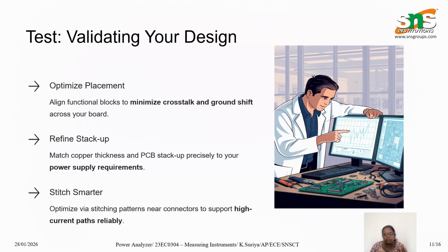Power analyzers also help engineers during testing and validation of PCB designs. They assist in optimizing component placement, reducing crosstalk, improving grounding, and selecting the correct copper thickness for power handling. Proper stitching near connectors also helps support high current paths safely. These improvements increase the reliability and ensure stable operation of the electronic circuits.